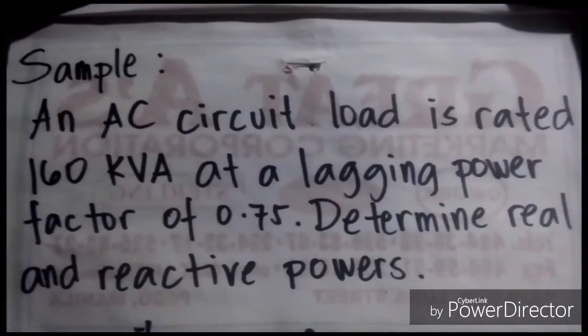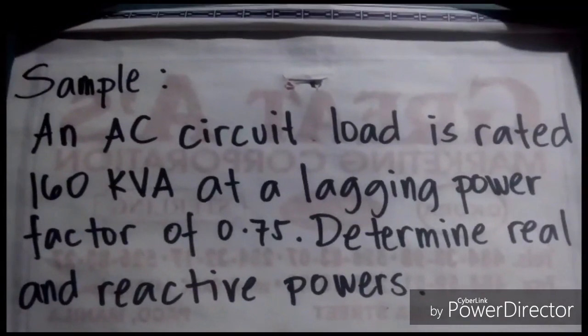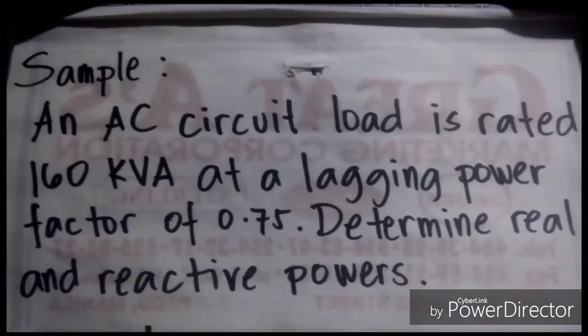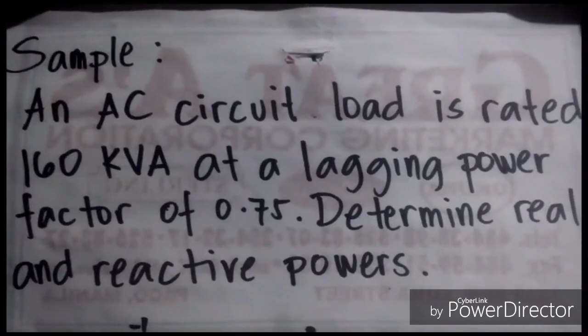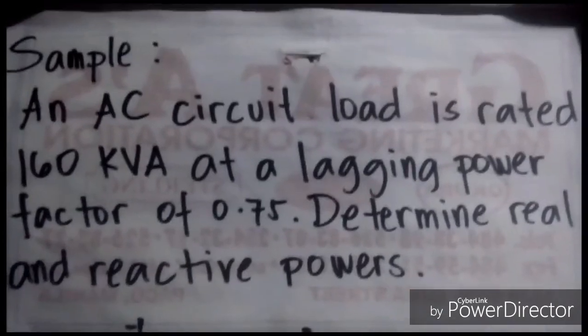I have another sample of finding the real or active power and reactive power. An AC circuit load is rated 160 kVA at a lagging power factor of 0.75. Determine real and reactive powers. In example number 2, we were asked to find the real or active power and reactive power.